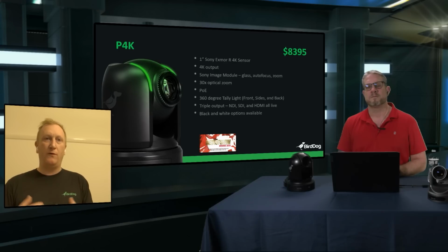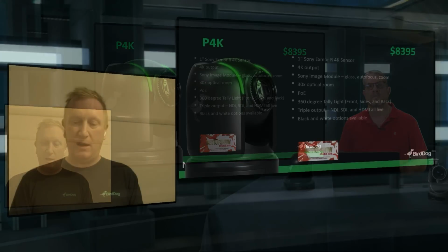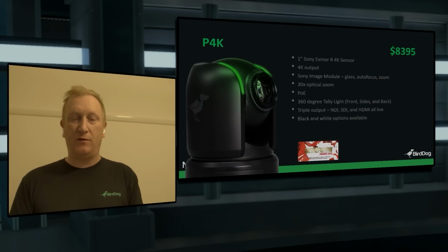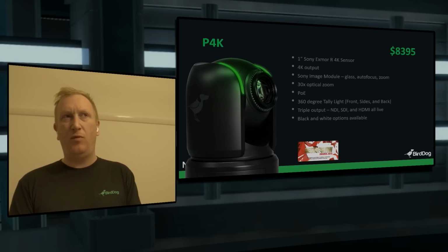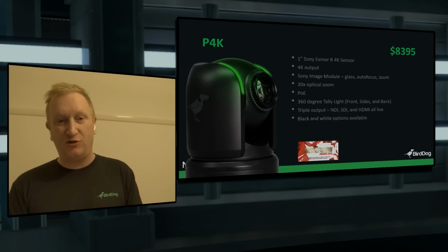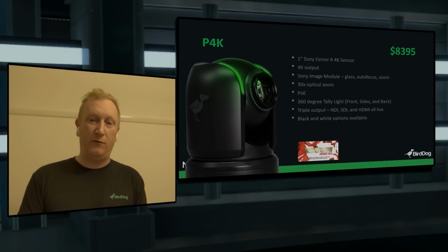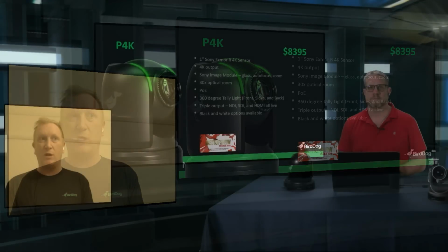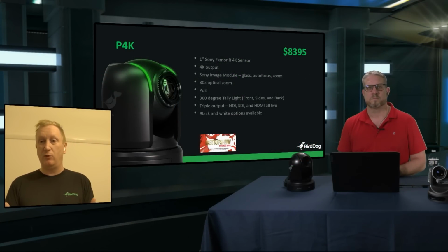Yeah, that's true. So like with all of our cameras, and this is the beautiful thing about them being networked, anywhere on the network you can adjust the camera, and all of our cameras come with a full color matrix. So you can adjust all of the red, green, blue, cyan, yellow, and magenta properties. You've even got Kelvin control on some of the cameras, and in the broadcast land, they call it shading or color painting the cameras, and we can do all that over the network without the need for any high-end tools. So some camera companies sell really expensive control panels for that. We can do it all through software, which is really a massive leap into the future.